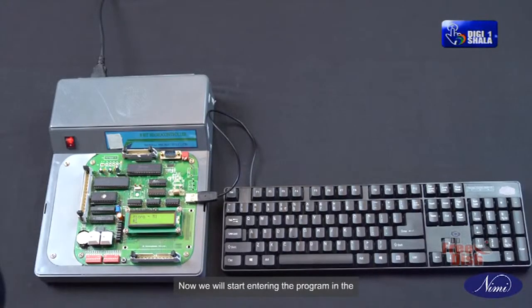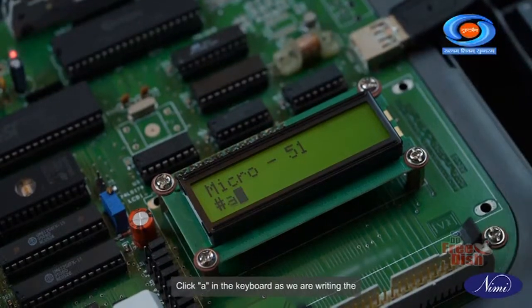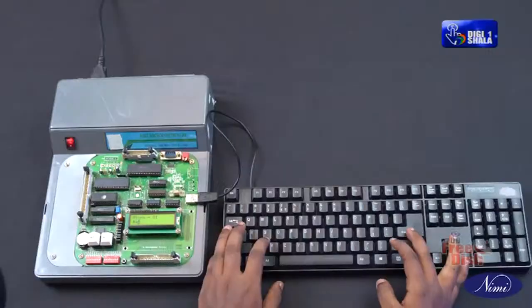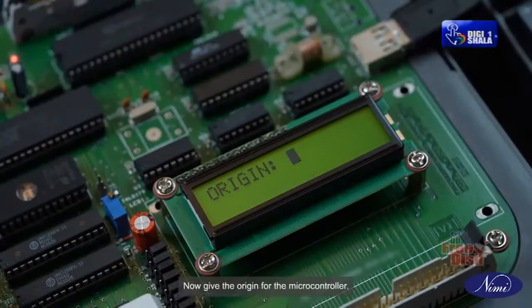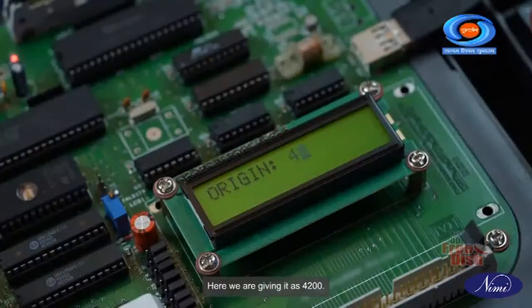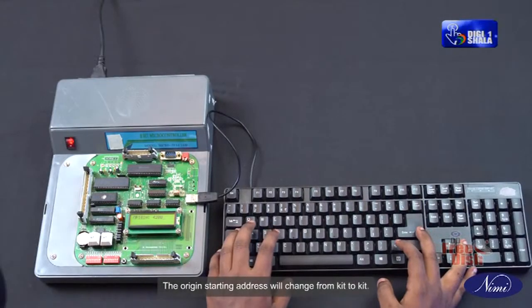Now we will start entering the program in the microcontroller kit. Click A on the keyboard as we are writing the code in assembly language. Click Enter to proceed. Now give the origin for the microcontroller. Here we are giving it as 4200. The origin starting address will change from kit to kit.